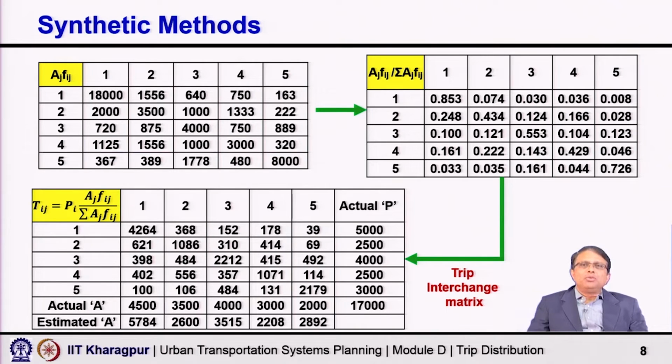Okay. How do we compare these distributions? What we will do is calculate the trip length frequencies now. What does it matter? That means we are not going to compare zone to zone values. We cannot do that, because what is our objective? Why are we not doing the cell to cell comparison now? Because our basic purpose at this stage is the calibration of the friction factor, time versus Fij value. That is our target.